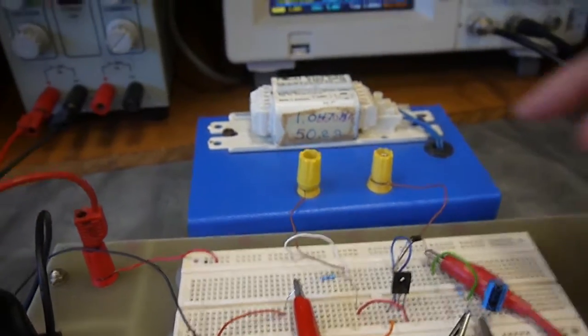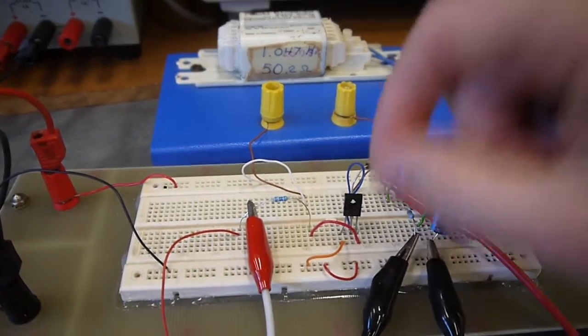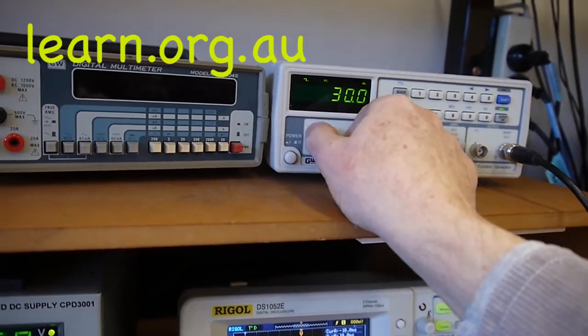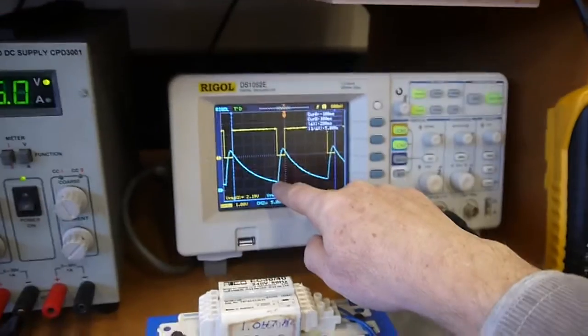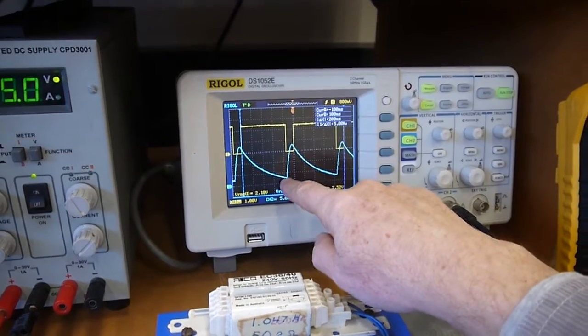So that's our demonstration then, to show with a simple inductive circuit and a switch. We could have even used a piece of wire and tap, tap, tap, tap, tap, and we would have seen a similar effect here if we could have tapped it fast enough. Because I am working with quite low frequencies, I mean 220 Hertz, we can take that right down to even 10 Hertz, and we end up with a lot of ripple across that capacitor, but we've actually still got a little bit of voltage gain.